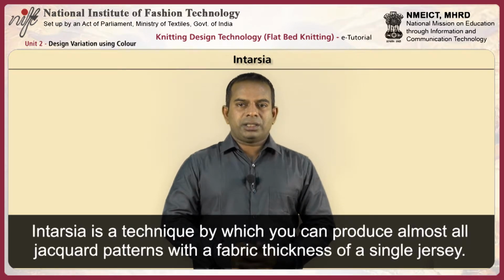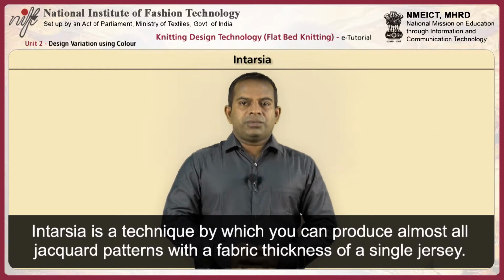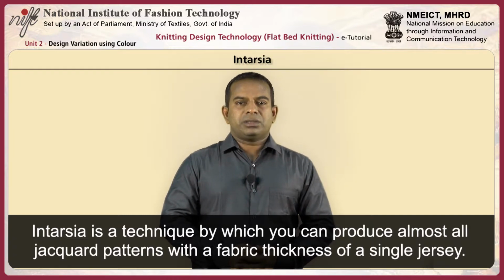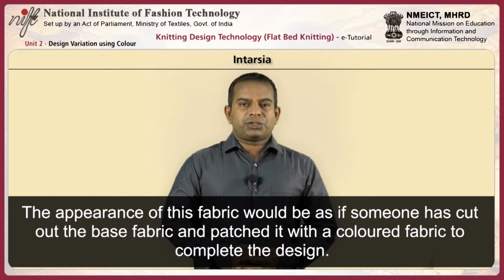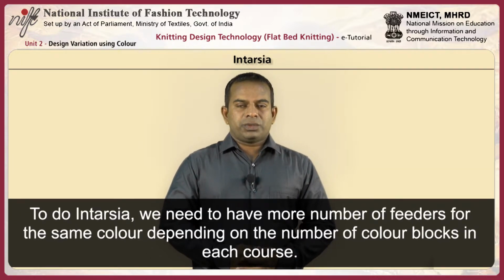Intarsia is a technique by which you can produce almost all jacquard patterns with a fabric thickness of a single jersey. The appearance of this fabric would be as if someone has cut out the base fabric and patched it with a colored fabric to complete the design. To do Intarsia, we need to have more number of feeders for the same color depending on the number of color blocks in each course.